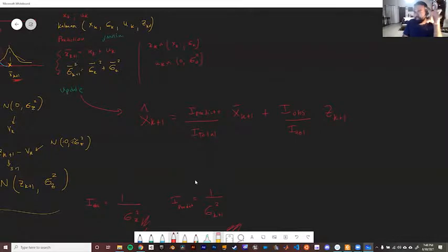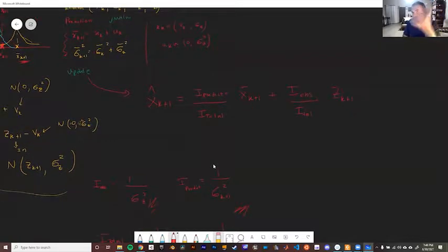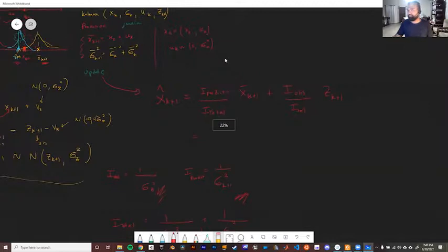What we are doing here is we are taking out of that total information, what is the weight that I'm going to give for the prediction and what is the weight I'm going to give for the observation. So whichever one is more powerful will factor into the final one, right? So it's kind of like finding an average, a weighted average between the prediction and the observation. And if you follow this, and you actually do the calculations, you end up with this Kalman filter algorithm, right?